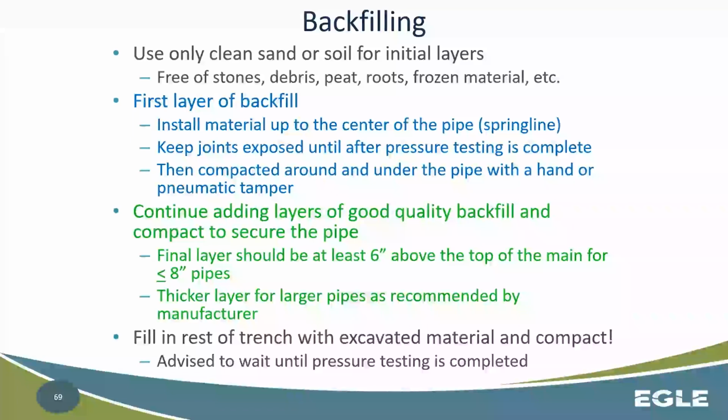Then your first layer backfill, install the material up to the center of the pipe, and keep the joints exposed until after the pressure testing is complete. Then compact the actual backfill material around the pipe, either by hand or with a pneumatic tamper, something like that. And then continue adding layers of good quality backfill and continue to secure the pipe.